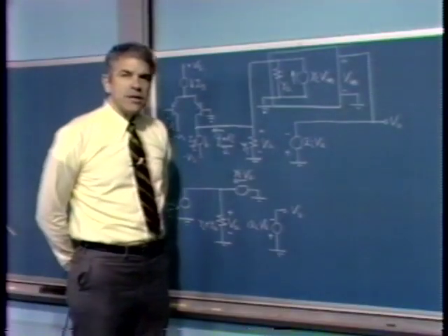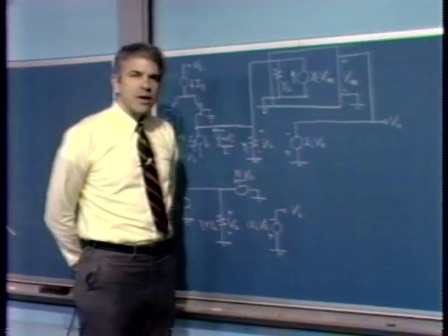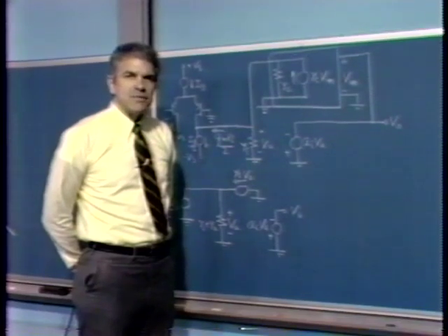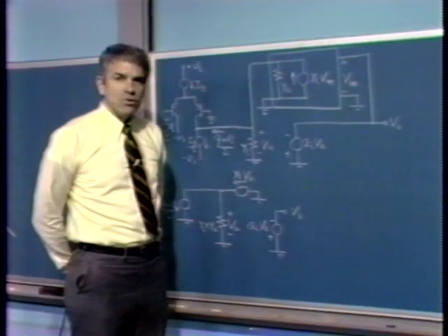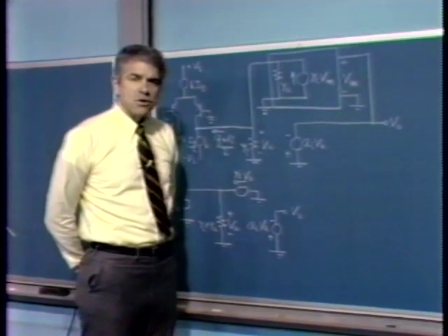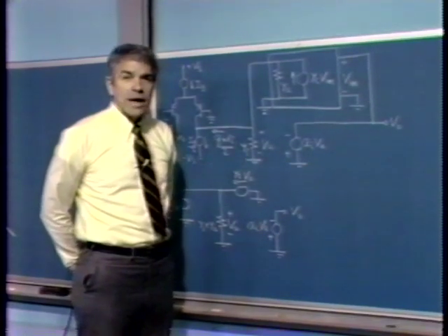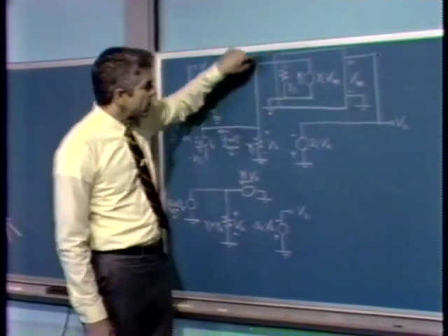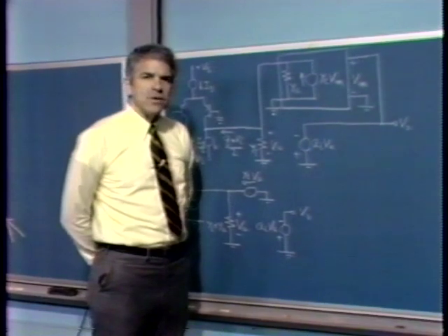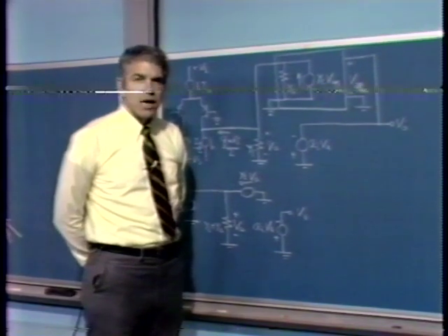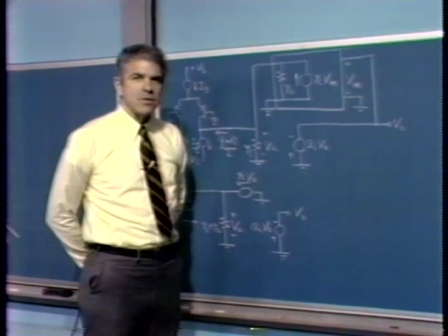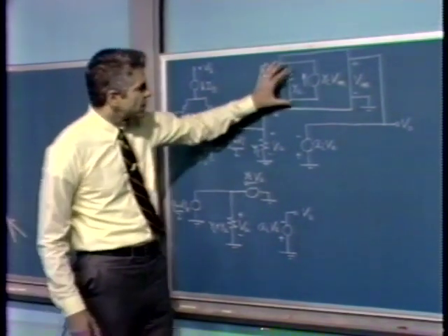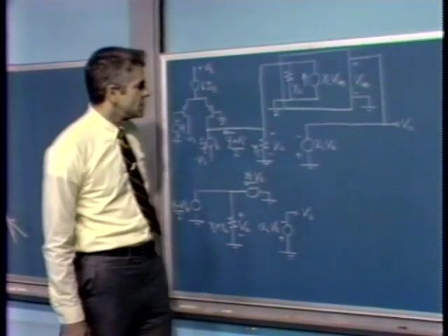Let me point out that my convention here is a little bit at variance with standard two-port convention, and I've chosen to do that simply to save some minus signs in the development. The usual convention defines currents in a two-port being into the network. The way I've defined my short-circuit transfer admittance is considering the current out of the network. My reason for doing that is just that it saves some minus signs in the development and hopefully some confusion. I've always found that I work a little bit better with fewer minus signs, so that's the reason for violating standard conventions in this development.